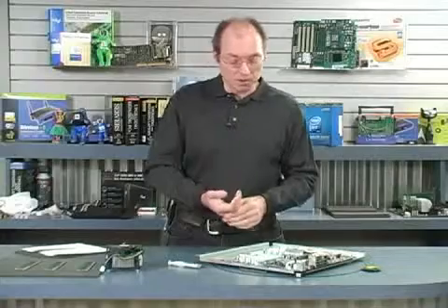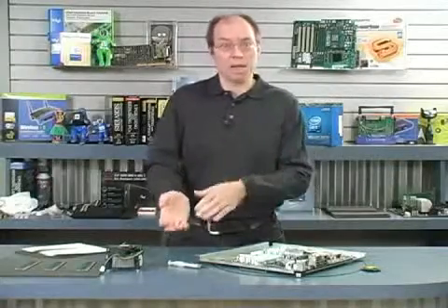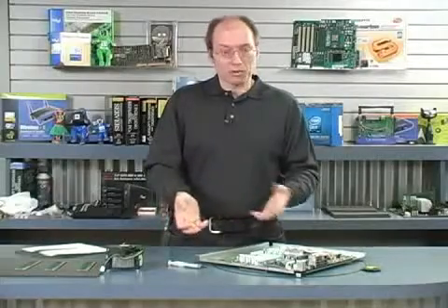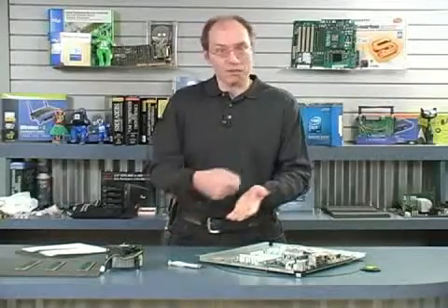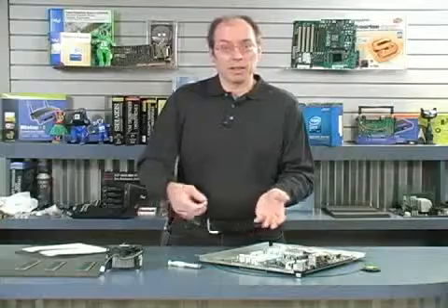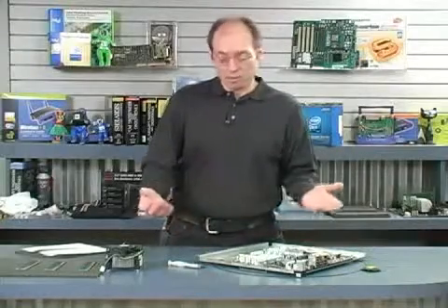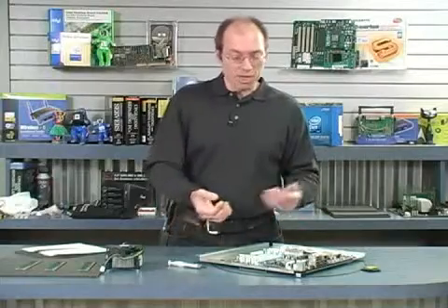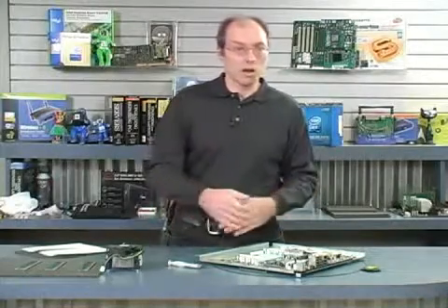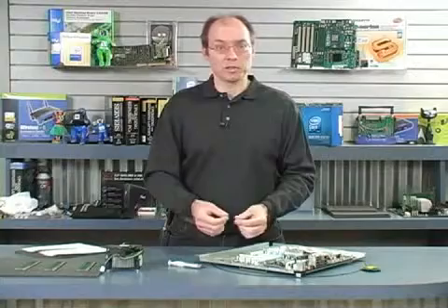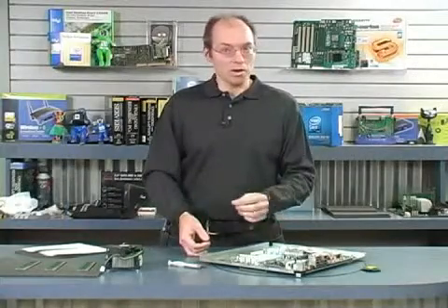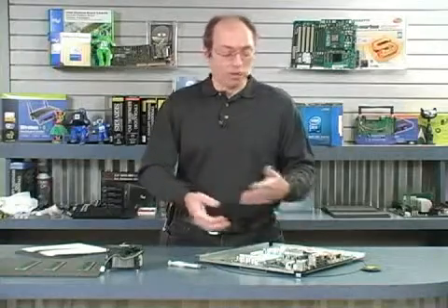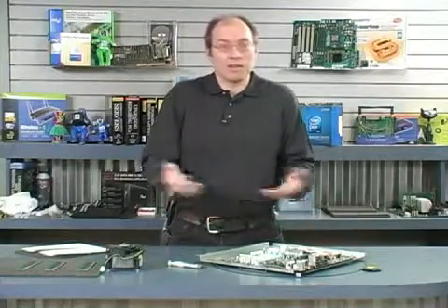Those are some of the drawbacks of the grease, and that's why the manufacturers like to use the phase change material. I've had people buy processors that come with heatsinks and scrape the phase change material off, never even using it, thinking that the grease is better. Either one performs pretty much the same thermally. In fact, I've seen numerous tests of hundreds of different types of thermal interface material, and rarely see more than a 1 degree difference in the actual operating temperature of the processor. It really doesn't matter.